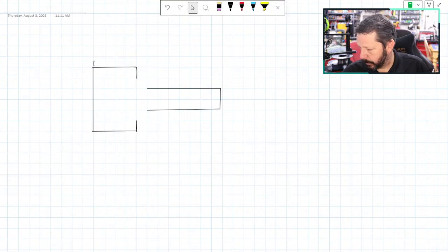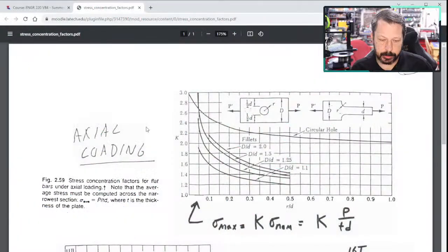They were over here, I think. Look how the charts, when you get on the left hand side, all these traces just kind of start taking off into these really large numbers. So it almost becomes vertical for these traces the farther left you go, which is controlled by the radius of this fillet right here.